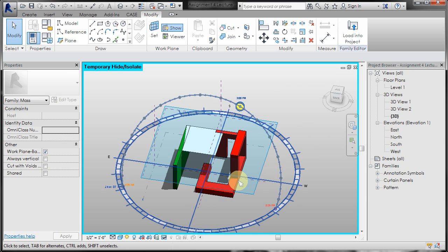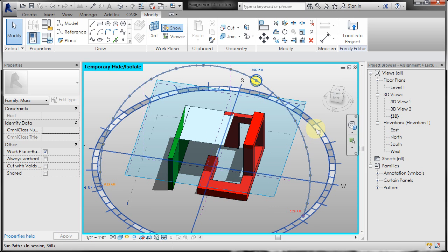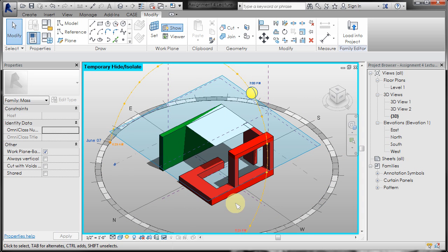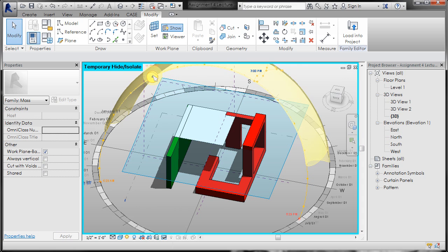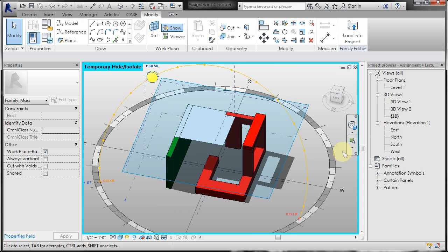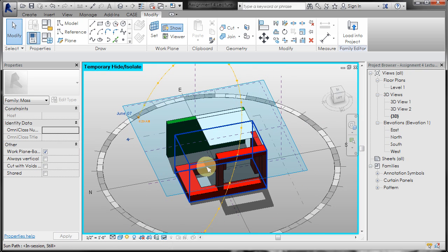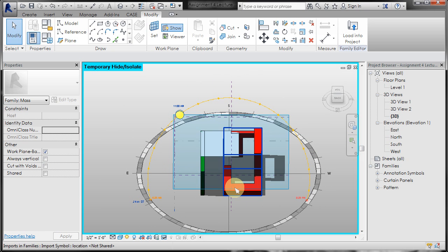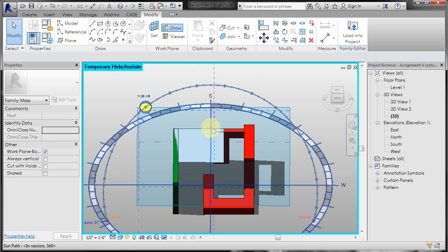I'm going to say that my goal is to have half of this sort of seating area shaded between 11 and 3. And you can see that I'm obviously not reaching that goal right now. If I swing this over towards 11, it's a little better there, but really I'm not reaching much, right? I'm going to have to go ahead and maybe pull this over and out. So to do that, you can come in and tab select the edges of this surface to move them.